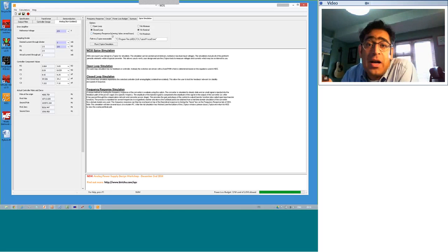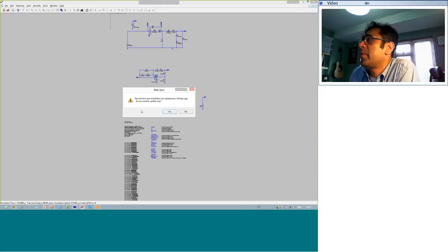The good news, though, is that that is a perfect simulation in frequency domain of your power supply without any mathematical modeling. So if you've got any errors in your mathematical model, it will show compared to what SPICE has simulated. For now, I can do a closed loop simulation in time domain because frequency domain will take a very long time.